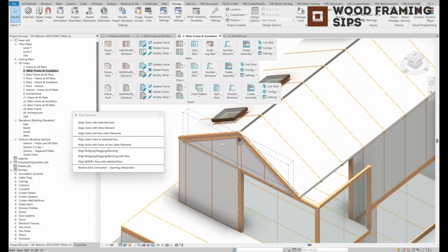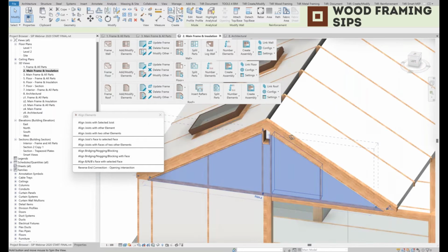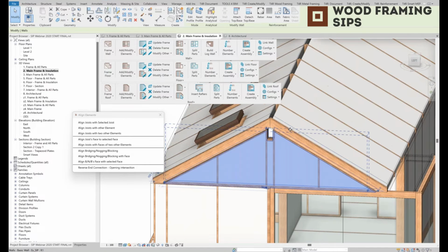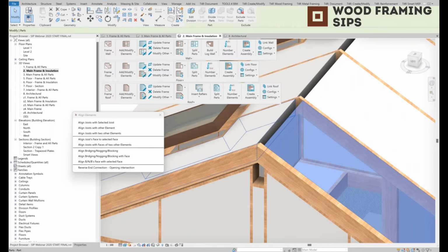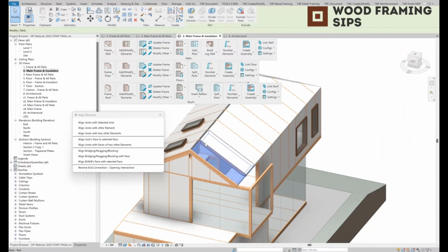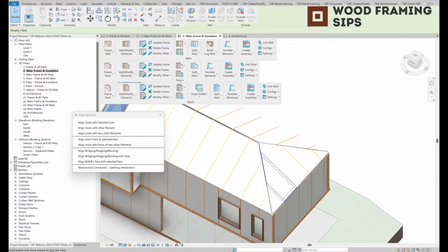So you can see that for the wall, I framed this beam pocket because I want to add the ridge now. And of course, I can add the ridge automatically. I will also frame roof parts to add these horizontal elements on the top and on the bottom of the parts. And I will add hip and valley rafters automatically.